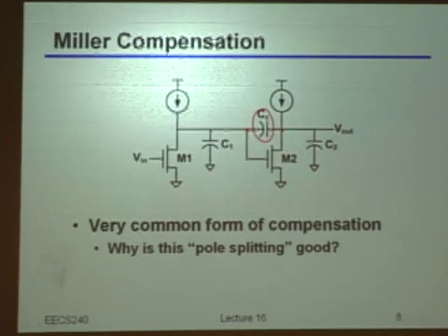So why is this working? It's a very common form. It's called pole splitting, right? So what is a nice technique? Do you remember what the benefits of this technique are? Exactly. It's getting both the advantages that we got with narrow banding and with the preamp technique. We are pushing P1 to lower frequencies, like we were doing in narrow banding, and we are pushing P2 to higher frequencies at the same time.